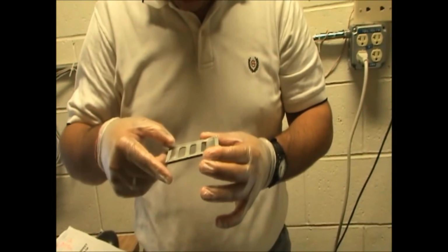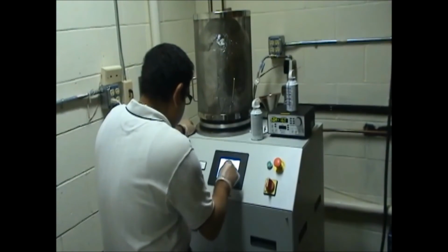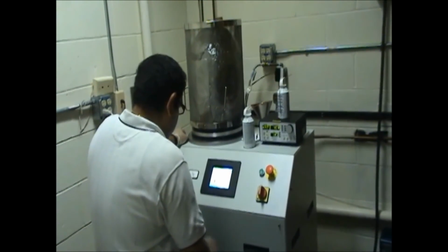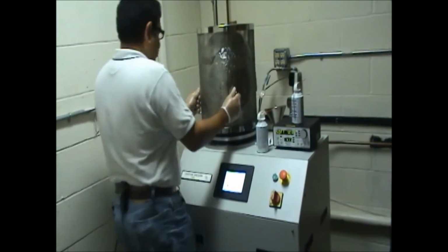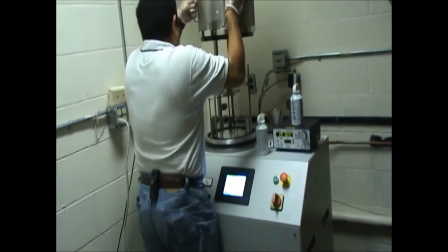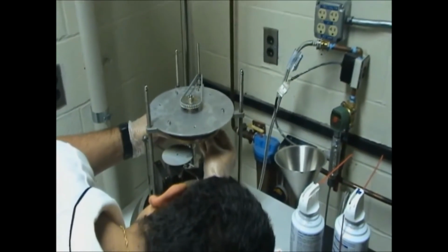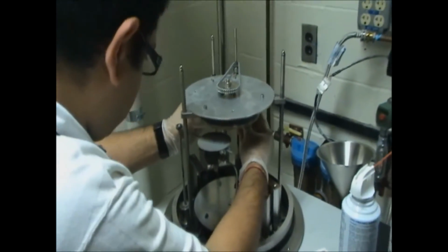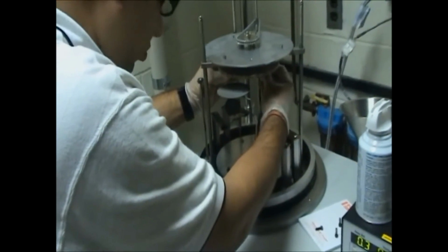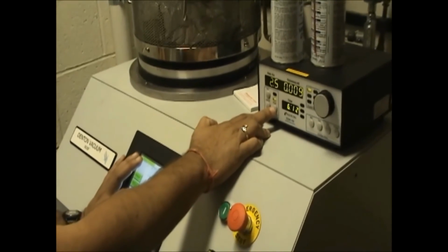After the first set of thin films, TPD and Alq3, are deposited, the evaporator is opened. The shadow mask is changed to deposit thin strips of metal crossing the top, and lithium fluoride and aluminum are loaded into the evaporator. The evaporator is pumped down again, and more thin layers are deposited onto the slide.